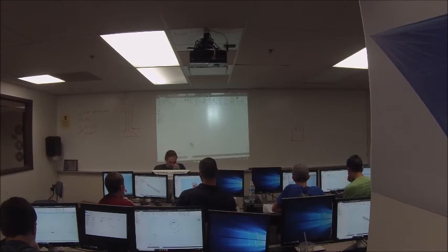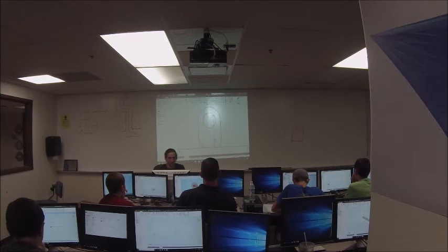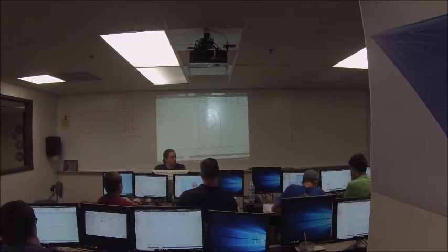Also, if you look down in the bottom right-hand corner when you're in a sketch, you'll see where it says fully constrained. In other words, if I delete a constraint, now it says I need one dimension because it has 1 degree of freedom. Basically, this tells you how many degrees of freedom your sketch has. So that can help you narrow it down as well.